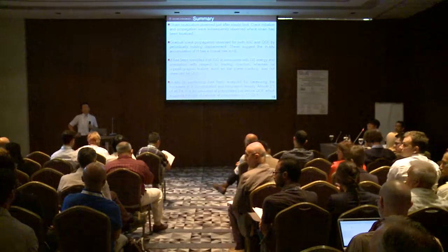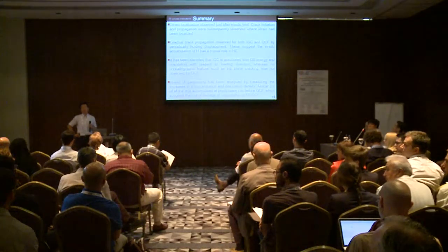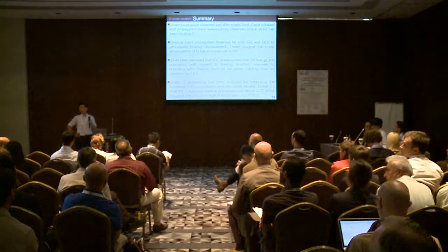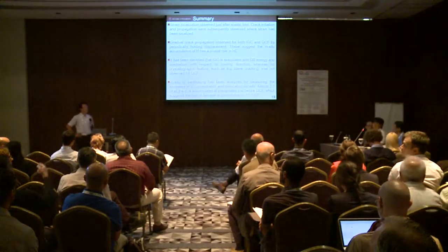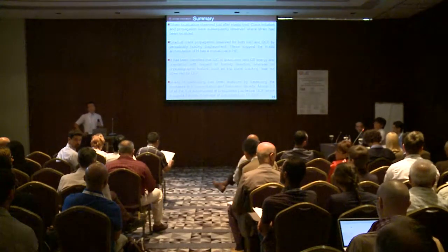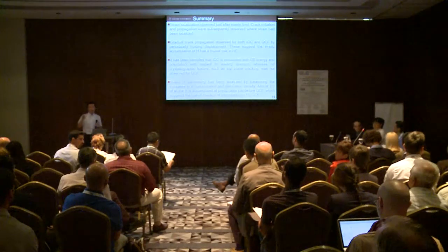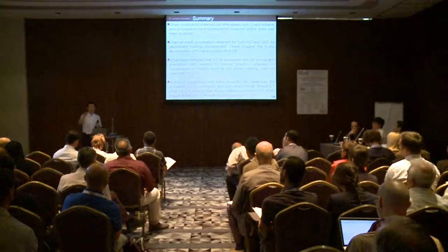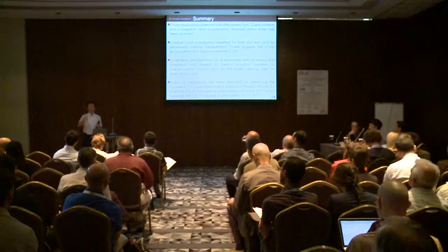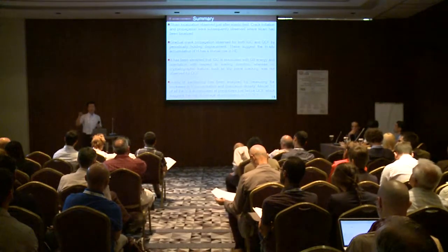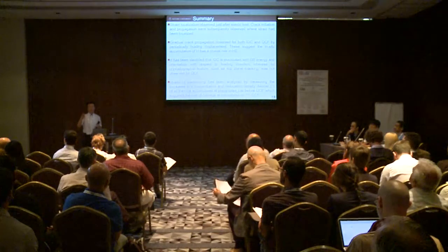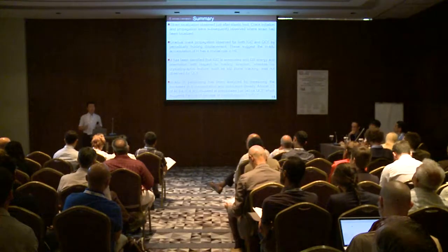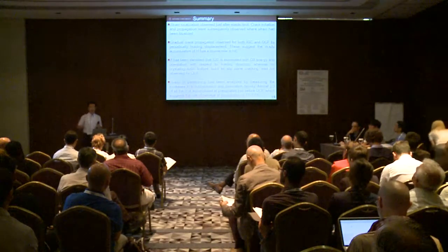My question is, why does hydrogen have a higher tendency to go to the vacancies when you have a higher plastic strain? You mean vacancies? Like you showed in the last slide, it is probably the balance between trap site density and binding energy. And in the case of dislocation, it's fairly low binding energy. And vacancies and nanovoids, we have a huge number of trap sites and also relatively high binding energy. So that's why hydrogen goes to those sites.